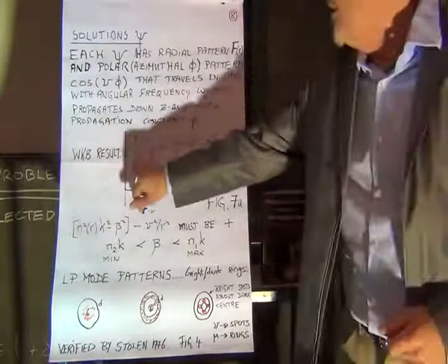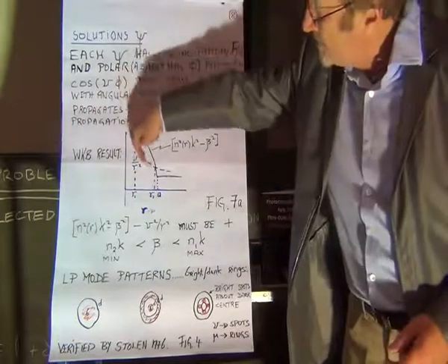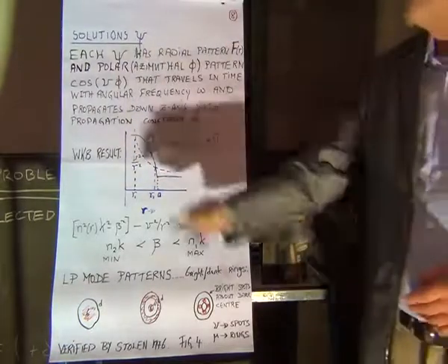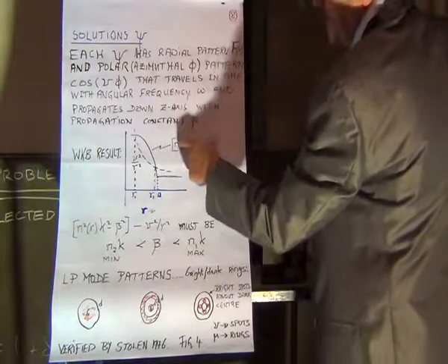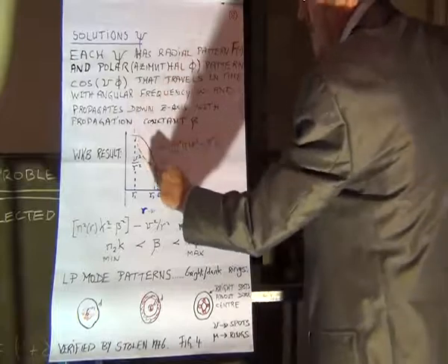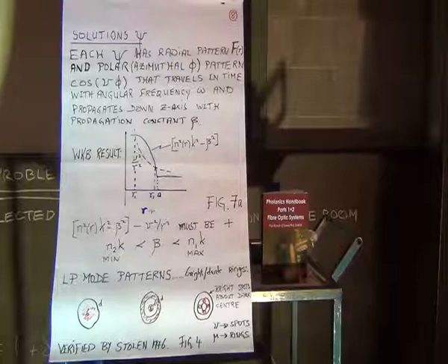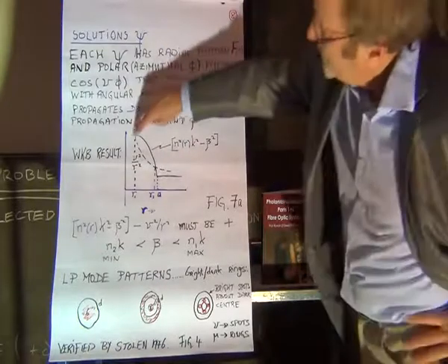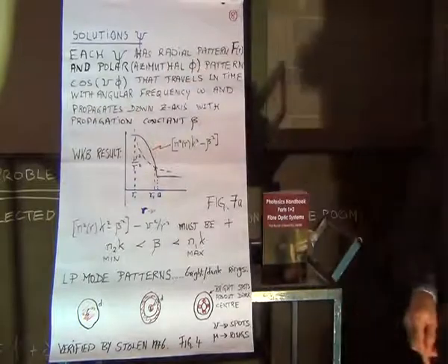Whereas the other quantity is just a 1 over r squared graph. And we all know what they look like. It's dashed there, an integer squared over r squared. Now for this quantity to be bigger than this, that solid graph must be uppermost. So all of the light is guided in this region here, from here to here, from R1 to R2.